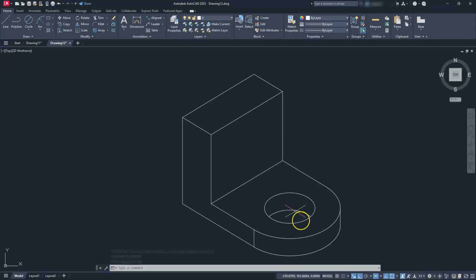Let's go ahead and switch to isometric right. So I'm just going to select the fly up here, go to isometric right, EL, enter, I, enter. I'll select this back midpoint, and then I'm going to come right over to that endpoint, just like we did before. Trim, select the cutting edge, which is going to be this line here, enter, then go ahead and trim off that portion there. Escape. Let's go back to the ellipse, so EL, enter, I, enter, go to that midpoint. I'm just going to type in D for diameter, so unlike selecting it last time, I can just type in D, 25. Okay, now we have this created.